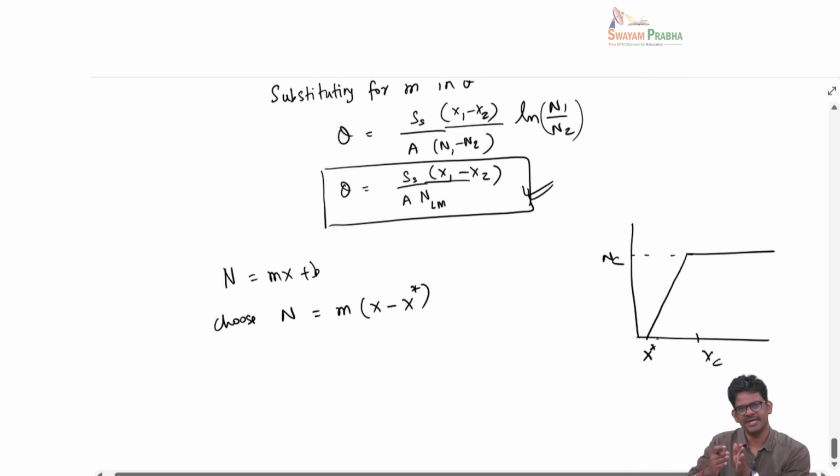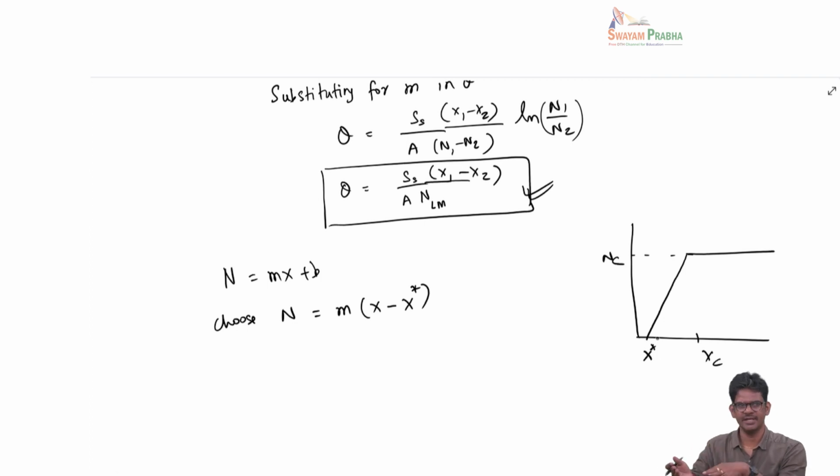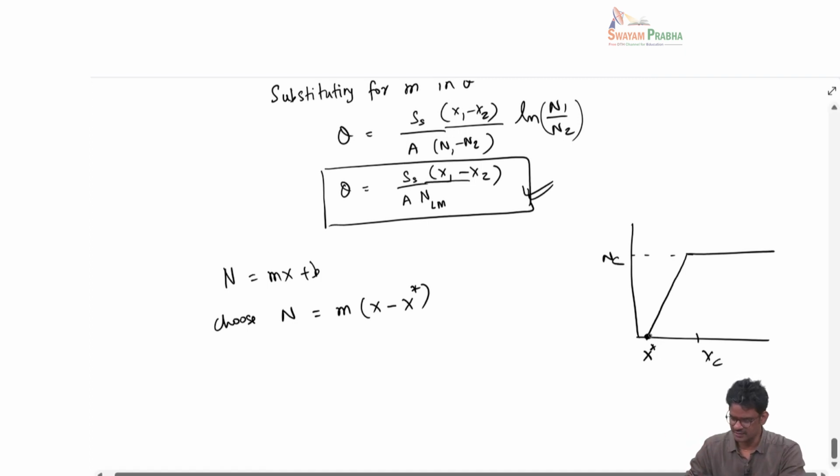So that means I am thinking about the falling rate as one single phase. I am not distinguishing between surface drying and internal moisture drying. The entire falling rate can be assumed to be a straight line. So this drying curve is constant and then falls linearly up to the equilibrium moisture content x star.